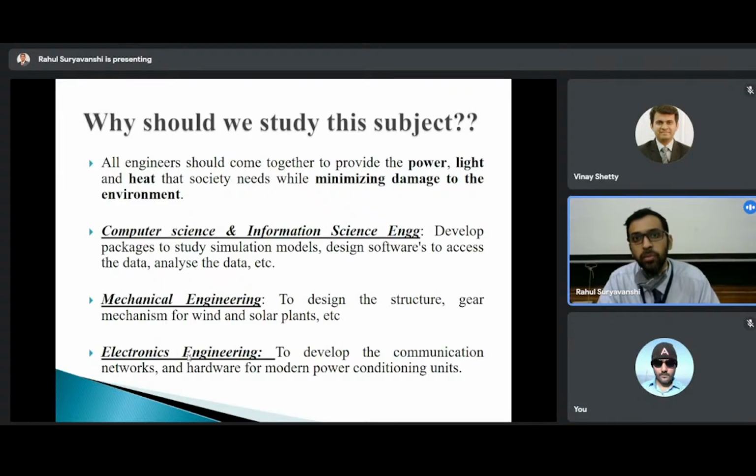When you want to install a plant, for wind turbines, if you want to install anywhere, there is something called a wind mast which needs to be installed. There are sensors, anemometers, what we call. There are sensors placed at various height levels. So that will decide the wind shear, what we say. So what is the amount of wind speed blowing at a particular height? And depending upon that, the prediction or the analysis has to be done,